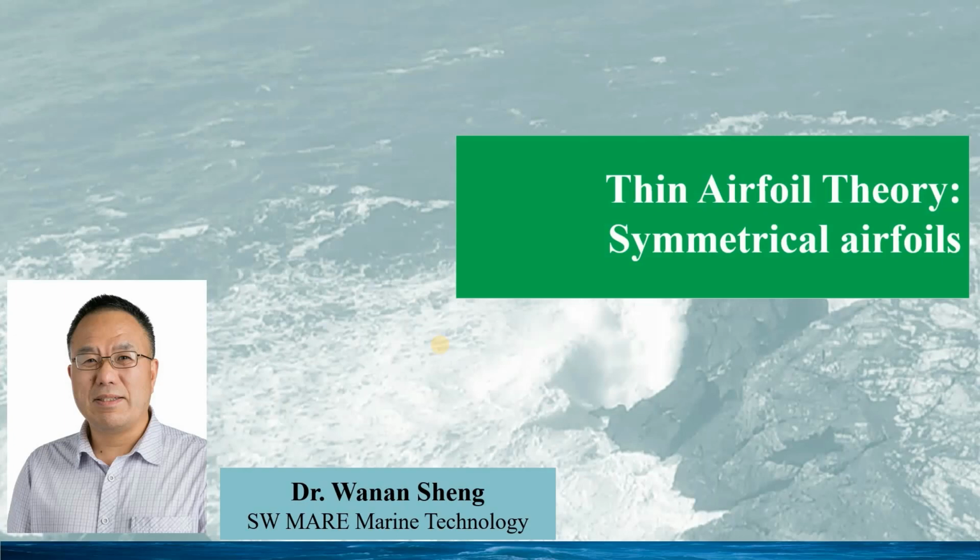This thin airfoil theory can be regarded as the first theory to prove the basic features of airfoils, such as the slope of the lift coefficient and the aerodynamic center. For simplifying the problem, here we solve the problem for symmetrical airfoils, and we will make some comparisons with the experimental data for different airfoils. These simple cases could be extended to more complicated cases, for instance, the cambered thin airfoils.